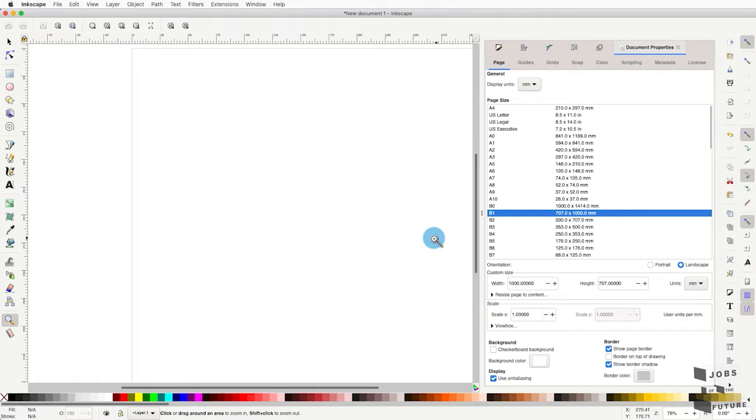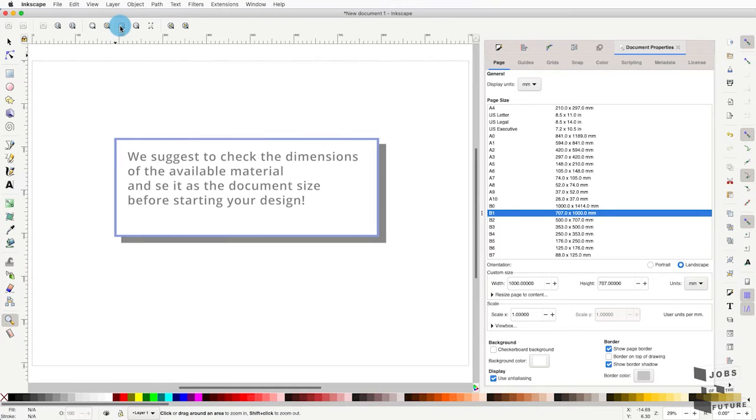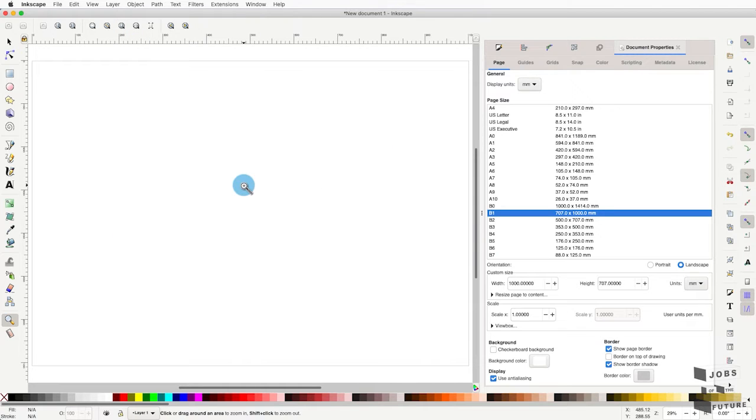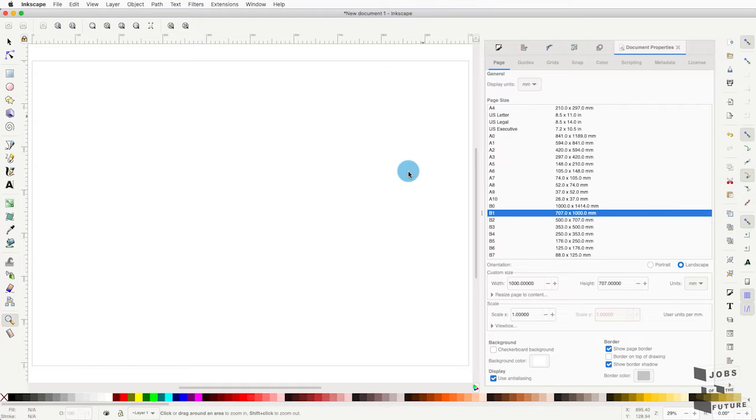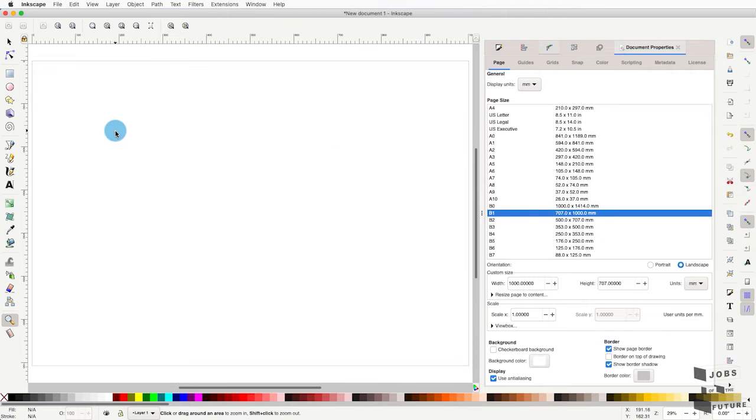And I measured that 7 centimeters diameter should be enough for every bottle to enter, because aluminium cans are standard size, but plastic bottles sometimes they have some difference in shape, in contour, and so 7 centimeters should work fine. So I can start to design the circle, the inner circle where the cans and the bottles should be inserted.